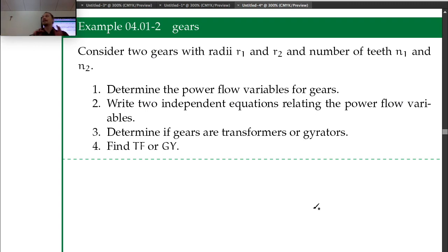So for instance, we'll talk more about this, but a lot of DC motors are more efficient when you run them at high speed, okay? And also, a lot of applications require something to move at low speed. And a lot of motors don't have a lot of torque.